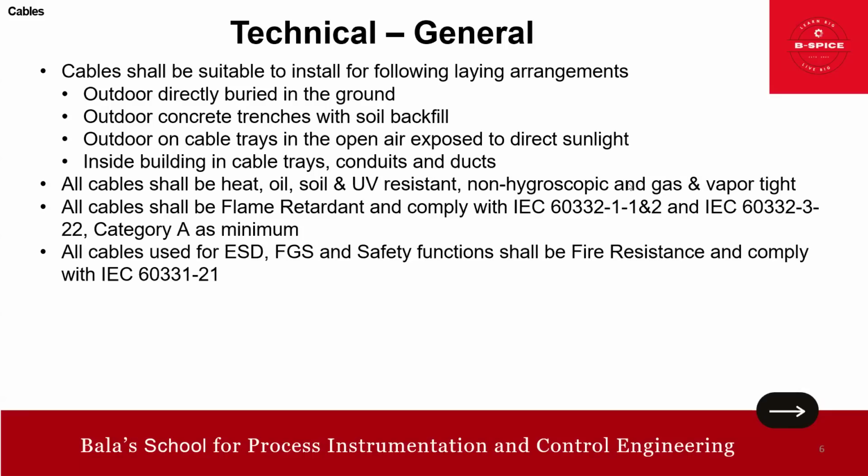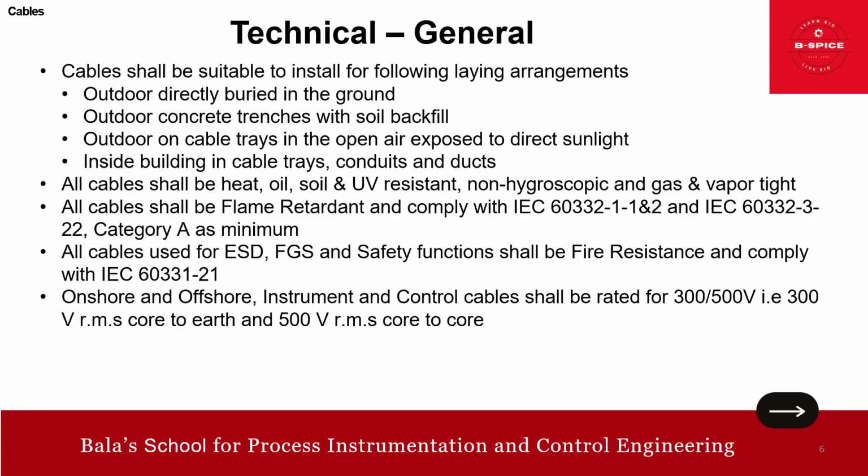Then all cables used for ESD, FGS and safety function shall be fire resistant and comply with IEC 60331-21. Okay, this one we have already seen, right? Yes. Then again, onshore and offshore instrument cables shall be rated for 300/500 volt. That is 300 volt RMS core to earth and 500 volt RMS core to core. So that is also something we need to watch out for.